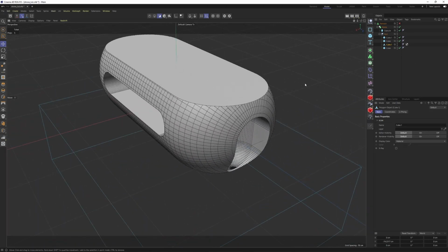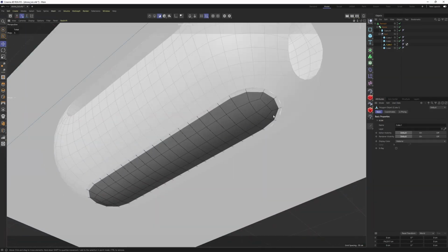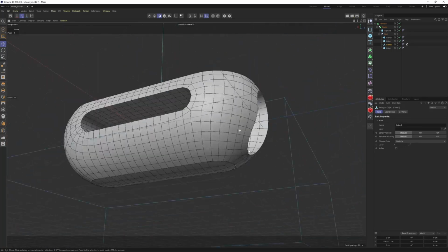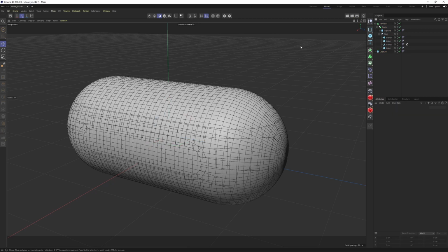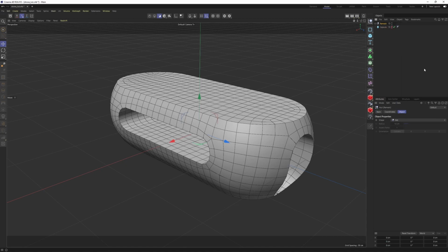Now let's see what's going to happen if I enable remesh. Perfect. This is exactly what we want, but we will just need some small adjustments. Before making this remesh editable, I'm gonna hold down Control, drag this capsule off, which will duplicate it. I'm gonna use that for projection later. So for the moment, I'm gonna hide it and make the remesh editable. Hit C.